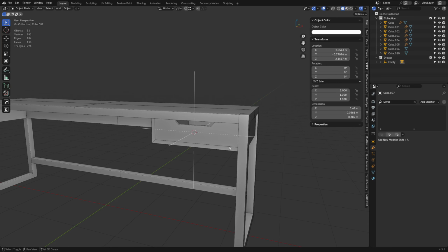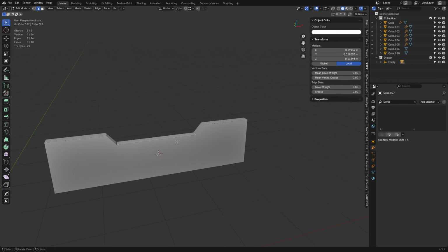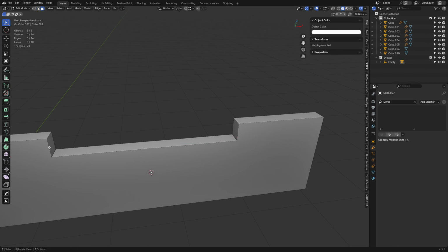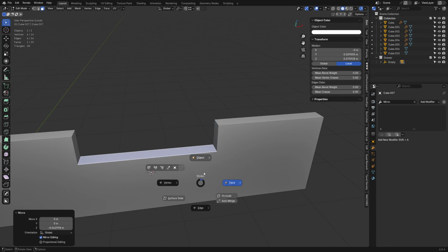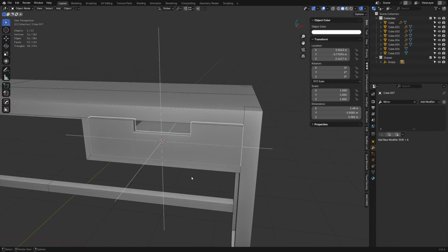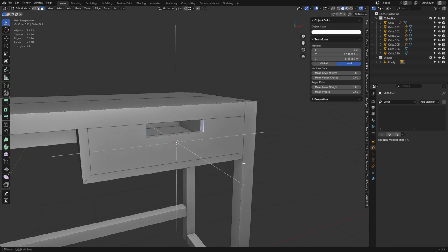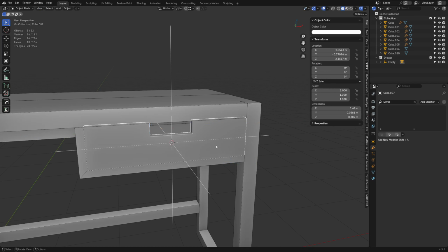That's it. So we more or less have the right thing going on here, except the actual object that we're creating, these are squared up. So we can use vertex snapping, square them back out. Not really a big deal. We can actually grab these two faces and press S and X, and we can adjust this, pull this down with G and Z. It's all flat, so it's very easy to move around and get it into the right positions and right sizes here. We still have the wrong proportions for this area. I'm just going to tweak it, and then we'll pretty much be done with that front section anyways.